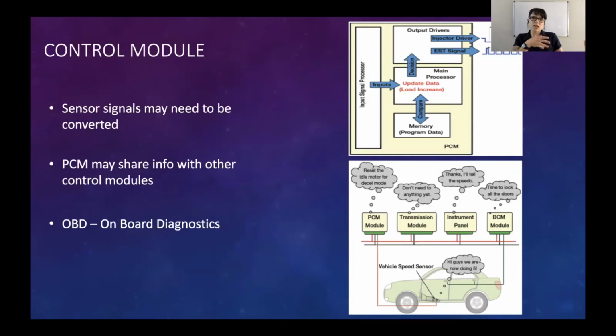Some of them you could use a scan tool, others you couldn't, and you couldn't use the same scan tool on a Ford as you could on a Dodge or something, so it was all over the place. Some of them, instead of using scan tools, you would put it into a diagnostic mode and it would blink a light at you, and you would have to read a little Morse code and get the code from there. And then a code 14 on a Nissan would be different than a code 14 on a Toyota. So there was stuff all over the place. Even though it was a step in the right direction, it got very confusing to work on cars.